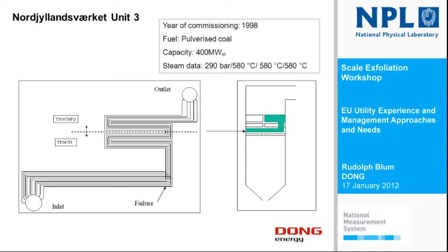But you know, these economical guys who are managing companies and so on, they found it was a little bit more expensive using fine-grained than coarse-grained, and we had a long discussion, and then I was put under pressure, and then from the original information about heat flux, we considered that it was such a good idea to keep down the investment cost. The first part of the boiler could be made by coarse-grained 347.